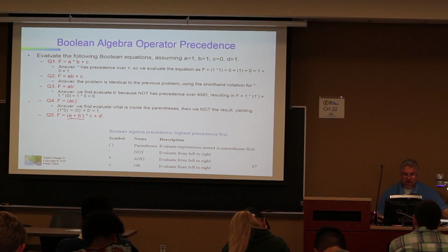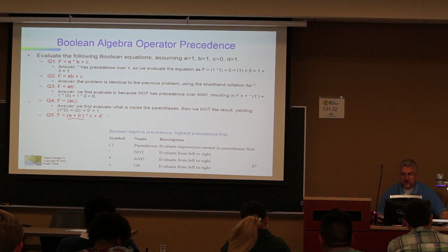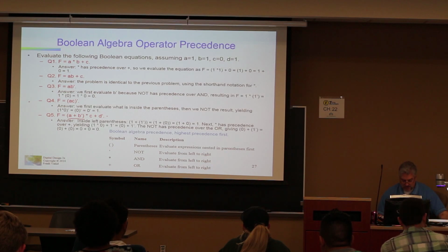All right, so A or not B, so that's a 1. Then we're going to AND it with C, 0. Then we're going to OR it with not D. D is 1, not D is 0. So the answer of all this is going to be 0. Let's see. Yeah, it goes through a lot of stuff, but we just did that one by one. Easy enough?